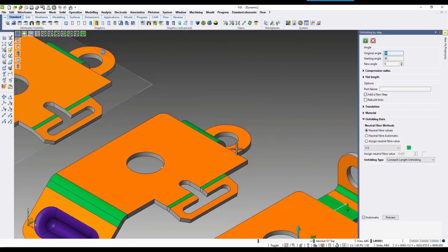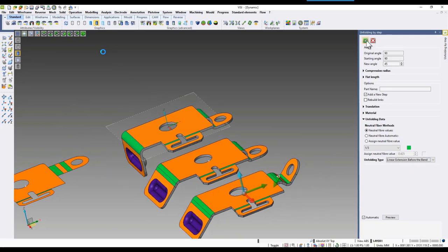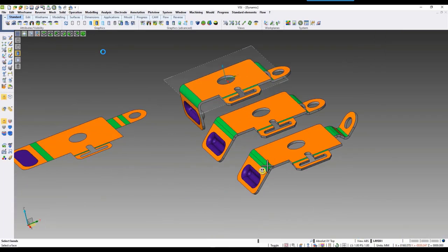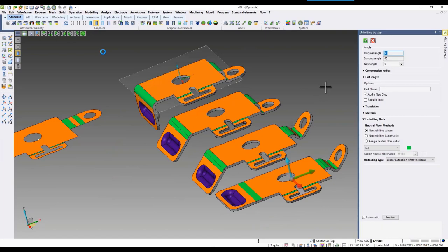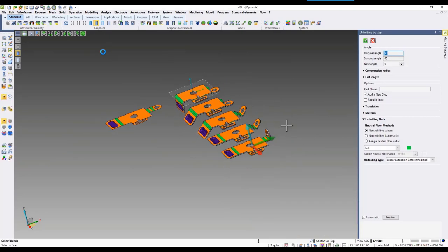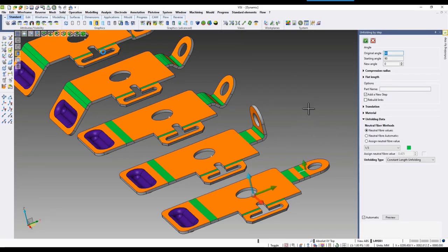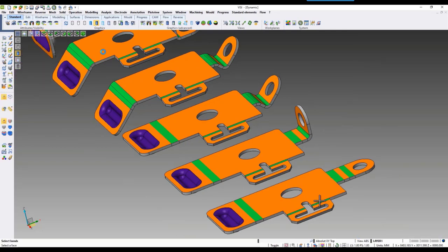And you can see it actually adds an extension blended edge there as well. So we can set the fold before and after, and it adds that edge in there automatically in relevance to the actual blended area. So when we unfold it, it actually will then simplify it. But before that point, you can add that edge in before or after the blend and start doing your unfolding process from that.